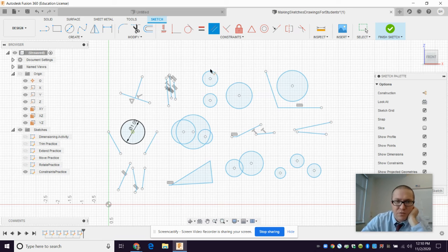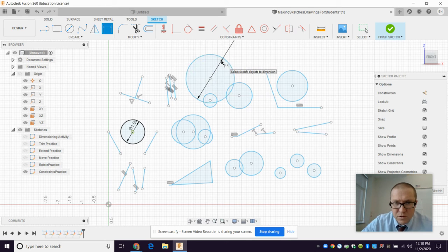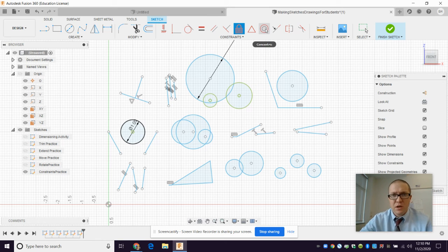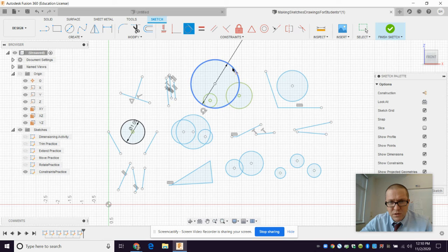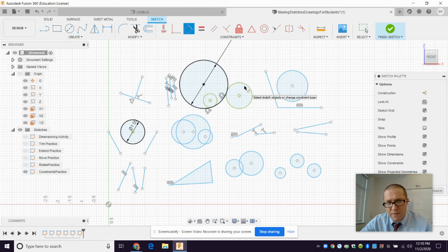This one looks a lot different. Circles 1 and 2, right? I'm going to hit escape. It says to dimension one of them to 2 inches, then fix the other two, fixes the lock. Right, this will fix these. When it turns green, that means it's fixed. You usually have to click the center point and the outside edge. And then tangent is right here. So this tangent to that.